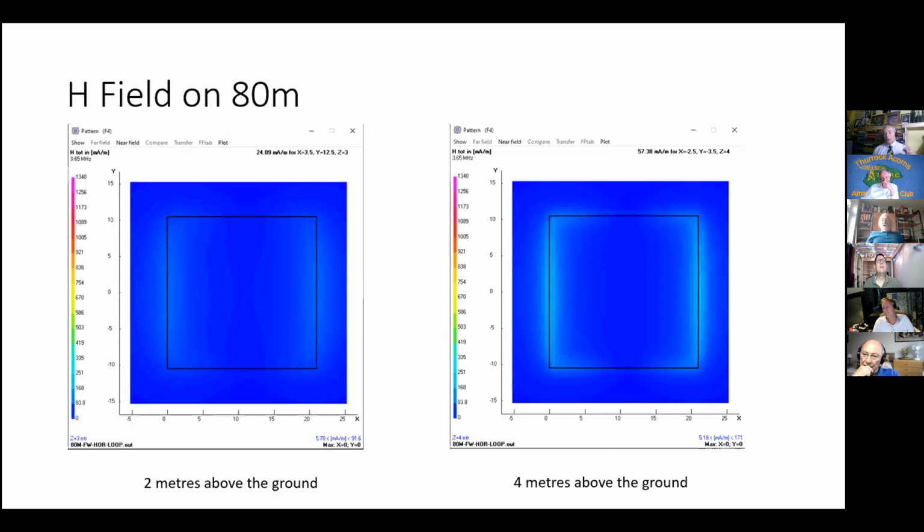The E field at the end will be much the same as if they were a quarter wave. The magnetic field will be concentrated between whatever trap element or loading coil is in them. So you could treat them as an antenna lying on its side, really. They're just an electrically loaded short antenna lying on its side. Okay, that's fine.